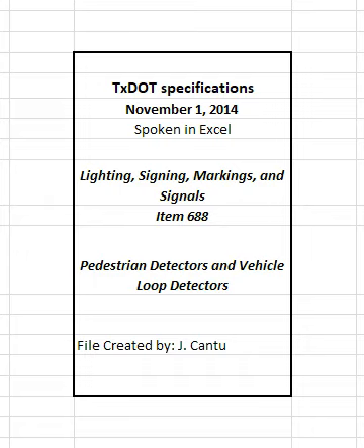4 Measurement. This item will be measured by the foot of saw cut containing loop wire and each pedestrian push button and controller unit. This is a plan's quantity measurement item. The quantity to be paid is the quantity shown in the proposal, unless modified by Article 9.2, Plan's quantity measurement. Additional measurements or calculations will be made if adjustments of quantities are required.